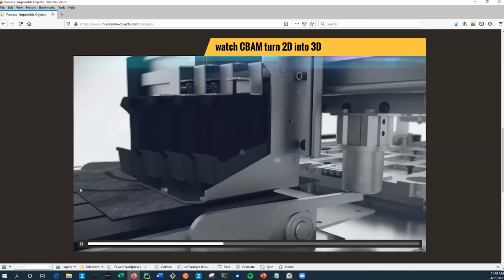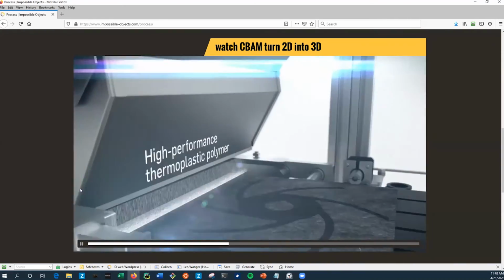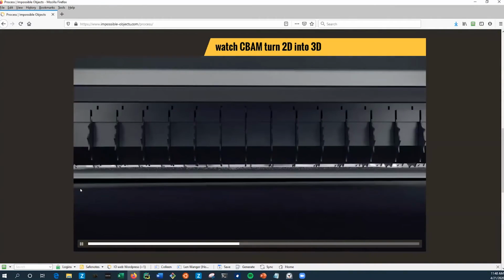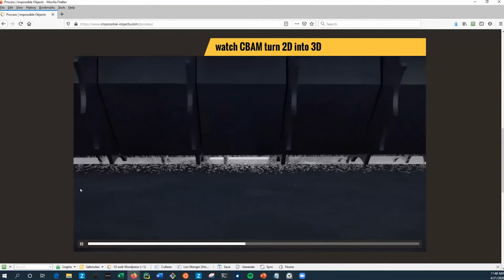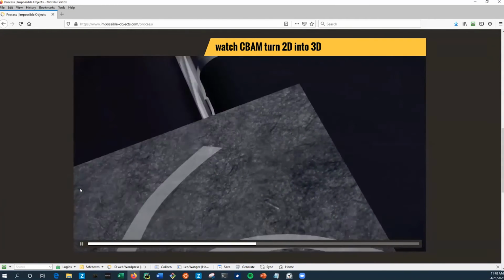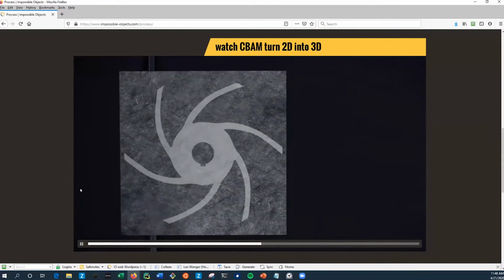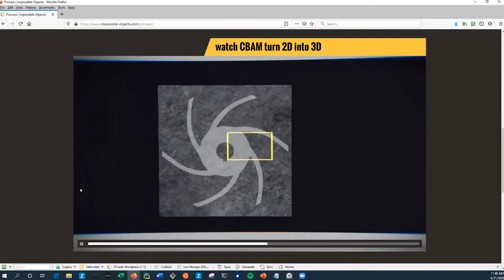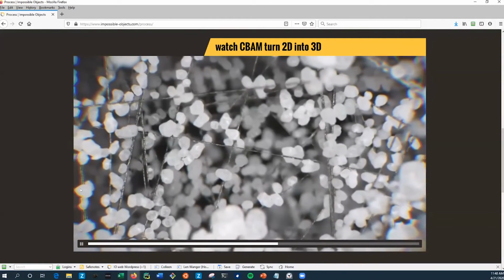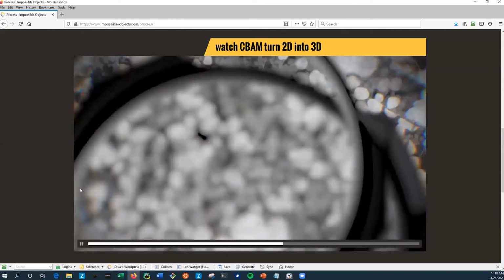This is actually not a glue or a binder. It's to help activate surface energies. We dust it with thermoplastic powder, and then we vacuum off the thermoplastic powder. It ends up sticking where we print it. So you end up with a sheet of carbon fiber with your thermoplastic selectively deposited on in the shape of your slice. Here's showing just some of the particles of thermoplastic embedded in the matrix.